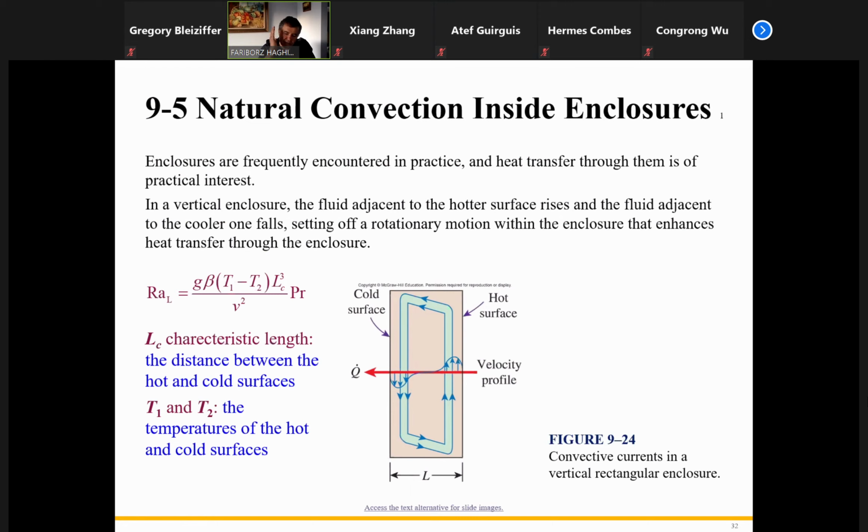So far we dealt with only one vertical plate, where the temperature of the plate was hot or cold. If I come back to the same physical phenomenon, it takes place between two plates, and that's exactly what happens between the two glass panes of a window. One of them here, one of them here, and we have an air gap in between. Look at the winter, the surface here outside is cold. At room temperature, the surface inside is hot. Again, we are talking about a small gap between these two.